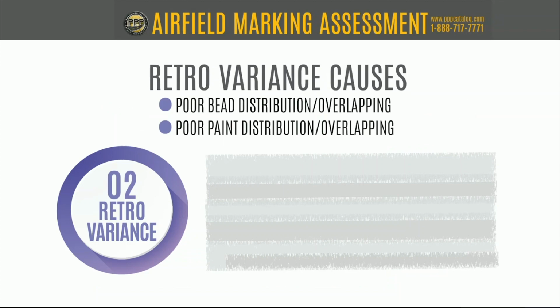Somebody has to be monitoring the material distribution. I don't know how many times I've trained or coached up an inspector, and they said, hey, we did the calibration and everything was good, and then we went out at night and it looked all streaky. What am I doing wrong? It's like, well, once you do the calibration, that's kind of step one. Then you've got to do this control strip and make sure everything is uniform. It doesn't happen by chance. You really have to have a lot of intent and attention to detail to get it uniform.